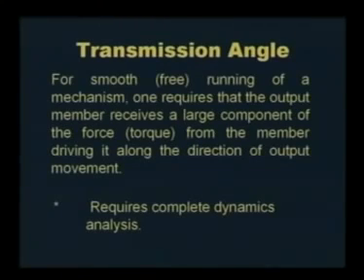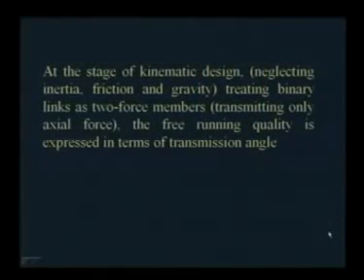However, even at the stage of kinematic design, what we do, we neglect inertia, friction and gravity and treat all the binary links as 2 force members, that is transmitting only axial force. With this assumption, the free running quality of a mechanism can be expressed in terms of what is called transmission angle.